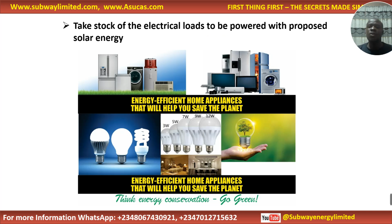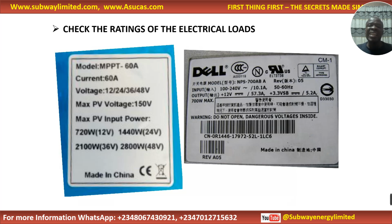Take stock of the electrical loads to be powered with the proposed solar energy. And I had already told you that we use energy-efficient electrical loads with a solar system, not outdated analog high-consuming electrical loads. So check the ratings of the electrical loads. The rating of any electrical load is always on the nameplate. When you look at any electrical load, you see it rated in watts. If it is not rated in watts, you see it rated in voltage and current. When you multiply voltage and current, you have the rating of the electrical load.